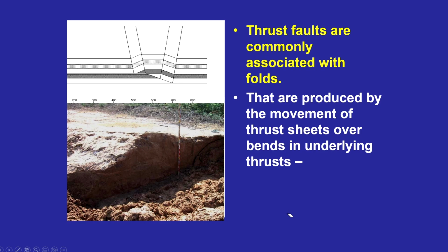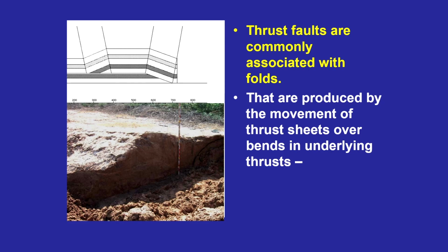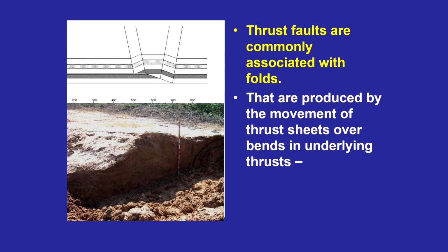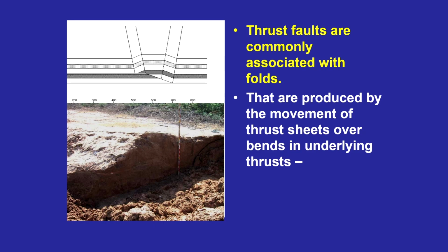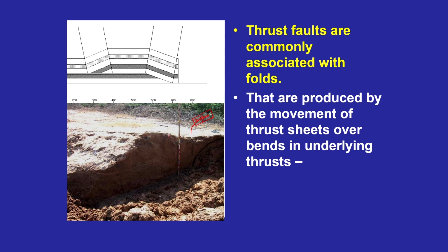Okay. So, now let us see what we were able to identify in the field after the 2001 Bhuj earthquake. This is on a very miniature scale, but can be correlated with a larger scale for the Himalayan domain. Okay. So, this was in the epicentral area where we saw a sort of landslip, which we call lateral spread, and that lateral spread resulted in deformation at the toe of the complete landslide. What we observed was very interesting: there is a thin whitish line over here. Now, this represents the surface that existed before the deformation. We were able to differentiate it easily because there was a little salt encrustation, because in the Great Rann of Kutch you usually see salt encrustation on surfaces.